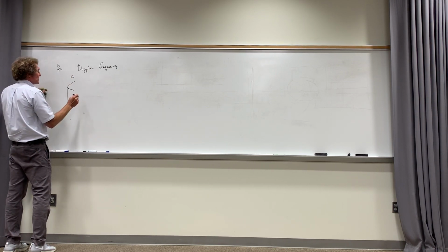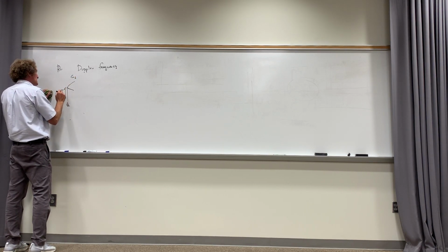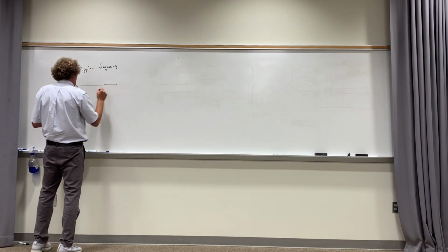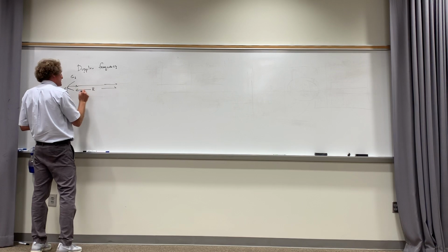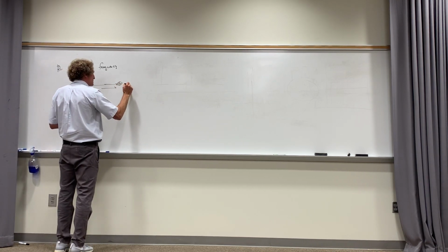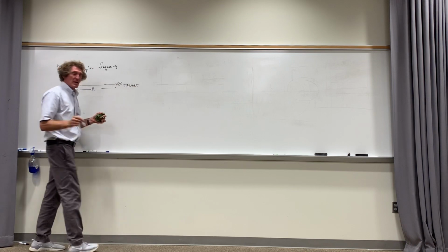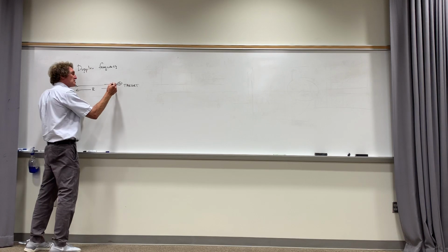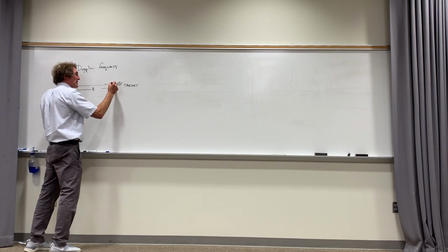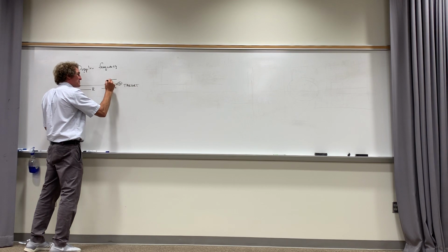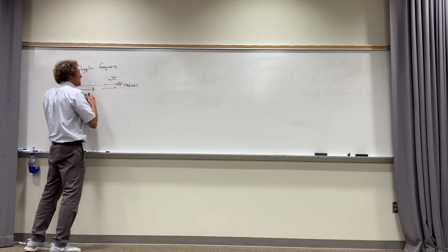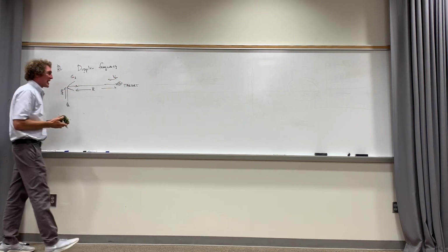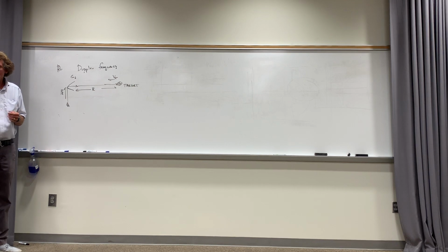This is the gain of the transmitter. You put in a certain transmitted power density, it shoots it off, and it goes a distance r, and it hits a target. Now, if this target is moving such that a component of the velocity is in the direction toward or directly away from the antenna, the radial direction, let's say it has a velocity V sub r. It's either going at it or not. With me on this?